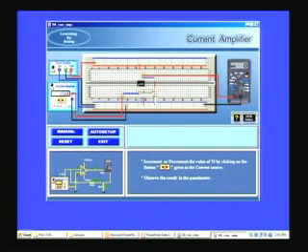The wiring is very simple. You can see this top one is the ground, this is the plus VCC, and this is the minus VCC, the blue line. So pin number 4 is connected to the bottom, which is the minus VCC, and pin number 7 is connected to plus VCC, and you have the input current here and the feedback loop, etc. So the wiring is exactly the same as what you have here, and so this is a current amplifier.